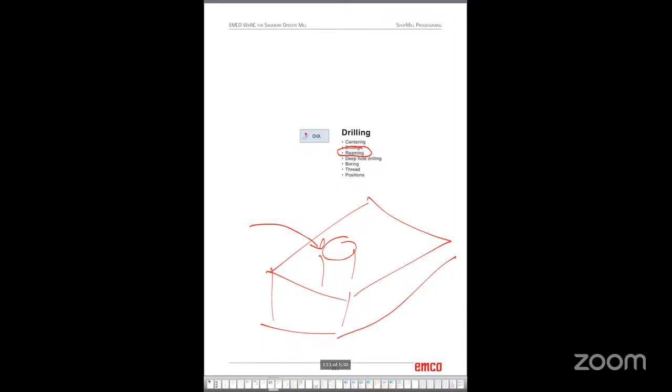In order to make a properly dimensioned hole, to make sure that the diameter is correct and the surface finish of the hole will be perfect, we will use the reaming operation. Your drilled hole will be like a rough hole. Using the reamer, we will convert this rough hole into a smooth hole, and into an accurate diameter hole, right?